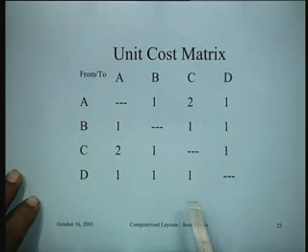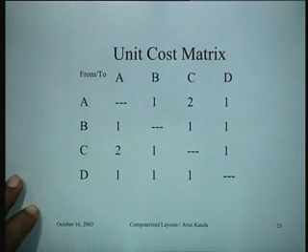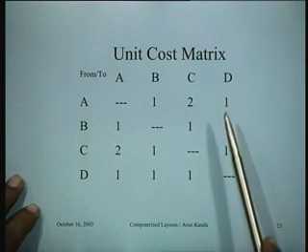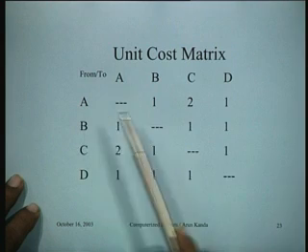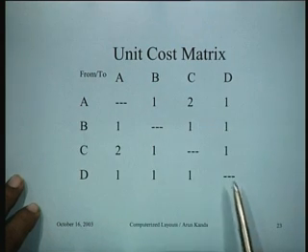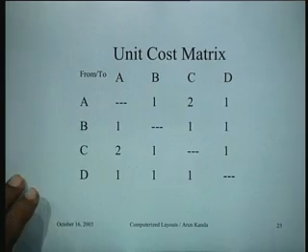So you have a matrix which we call the unit cost matrix. This is an input to the problem. You're still trying to identify the major inputs to the problem. If you have, for instance, all movements taking place by the same material handling equipment, then this matrix will be all ones, and you can in fact forget about this matrix, right?